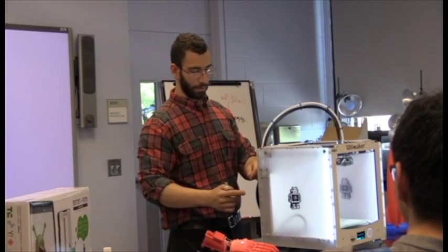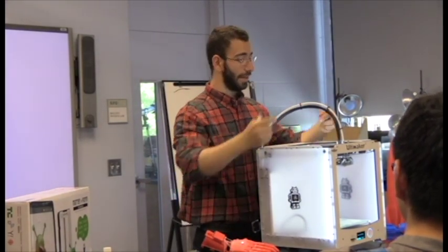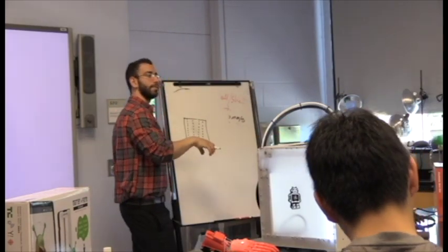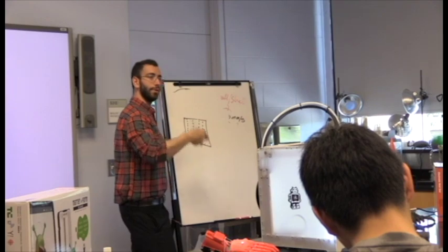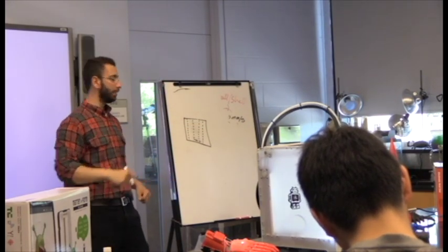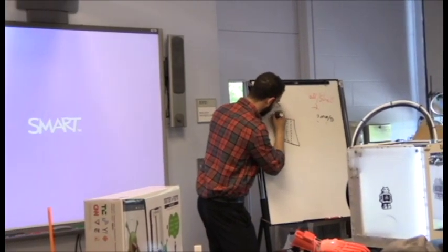It took the stepper motor just went reverse and took the filament all the way out after it heated the front. And why it did that is because, remember, it's solidified on the inside, so it melted that so it can pull out. Had you tried to pull it out, it wouldn't have worked because it's solidified on the inside. Okay? But there's a little tube, like a little white piece of plastic that looks like this.